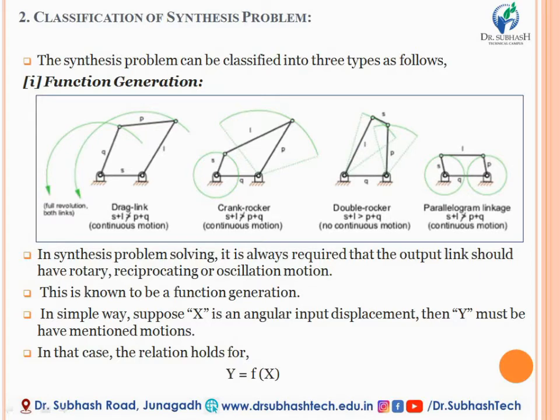So while solving any mechanism, it is very important which type of motion the output link has, whether reciprocating, oscillating, or rotary, and which periodic time is required to achieve it. The entire phenomenon, considering the periodic time with that particular output motion, is known as function generation.